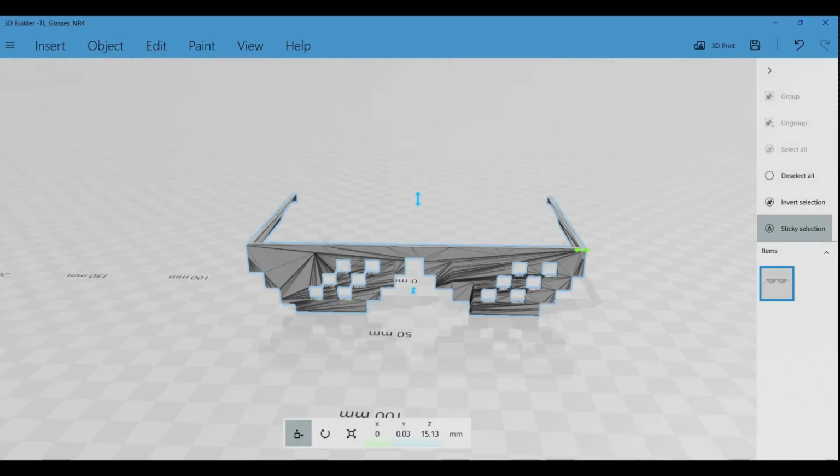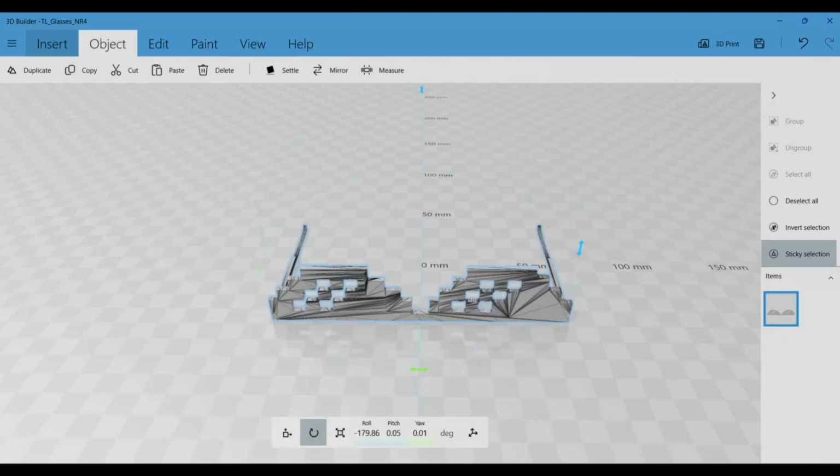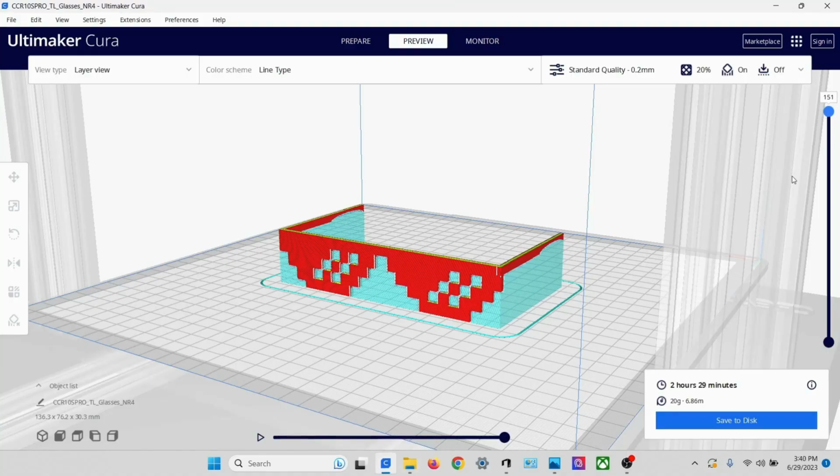Now we need to make sure the object is orientated correctly for 3D printing. Take this model for example. It can be made in various ways. The goal is to find the most efficient way that does not require supports while keeping print bed time low. You can see how the amount of support required to create this object, seen here in blue, is dependent on the product's orientation.